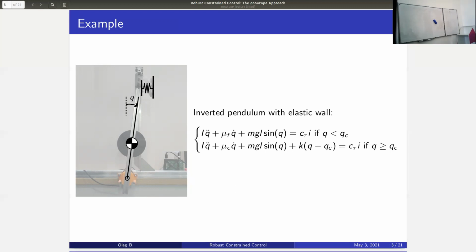But next, we try to find the inertia parameters of this system. If our system has a very simple shape, yes, we can. But when the shape of the moving part starts to be more complex, we need identification. We cannot calculate it. We need to identify it.